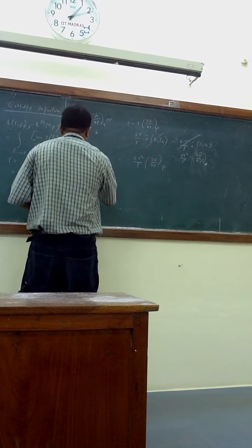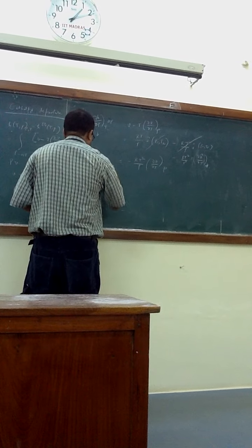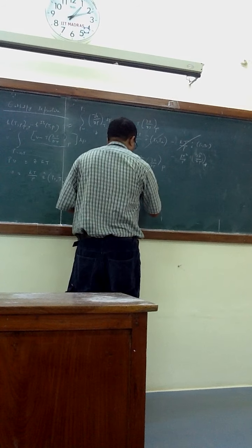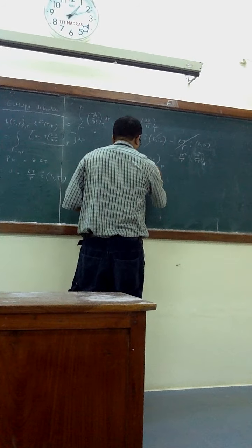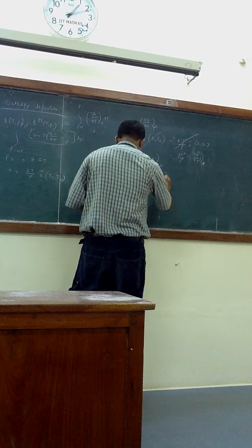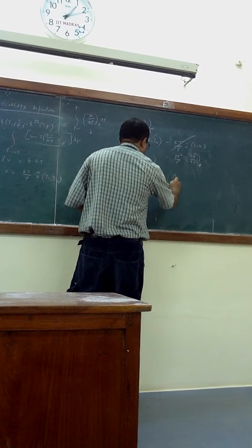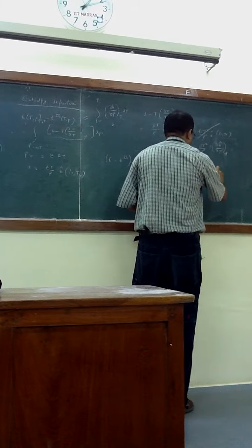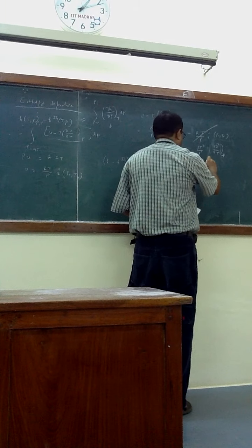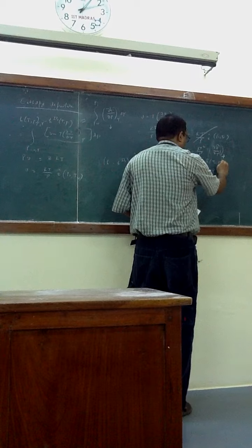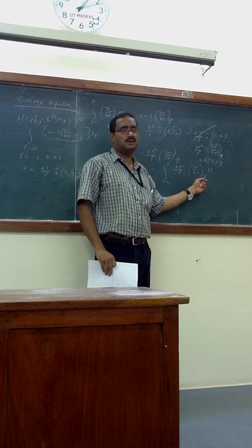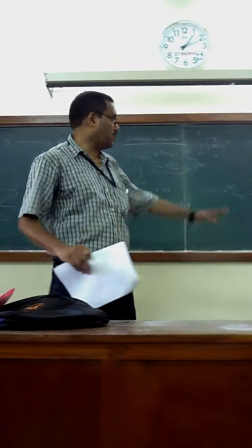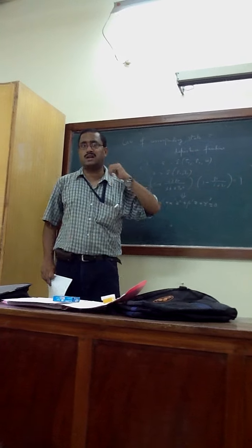So my departure formula is H minus H ideal gas at T, P should be minus, integral from P equals 0 to P, RT square by P ∂Z/∂T at P, dP. This is not complete, because this is a function of T and P. So you have to express everything in terms of TR, otherwise you cannot get it. So if you write a formula up to this, it is not the correct formula, right?